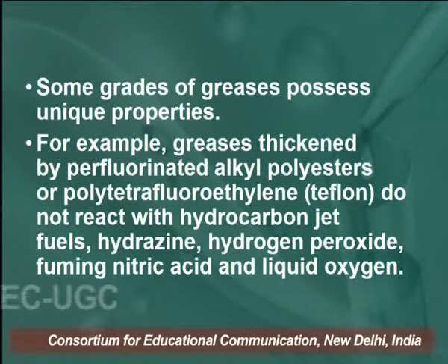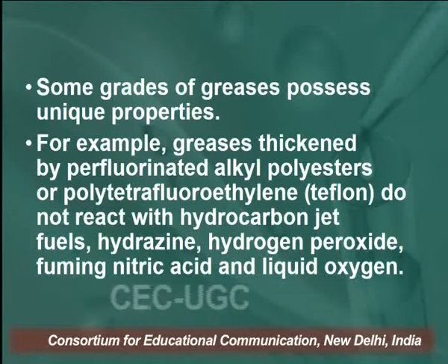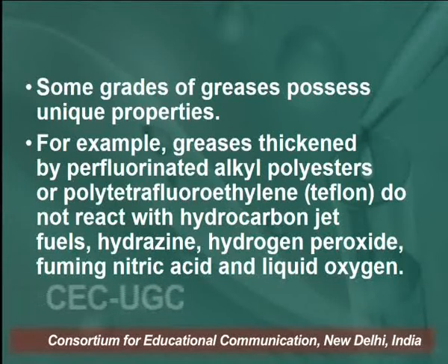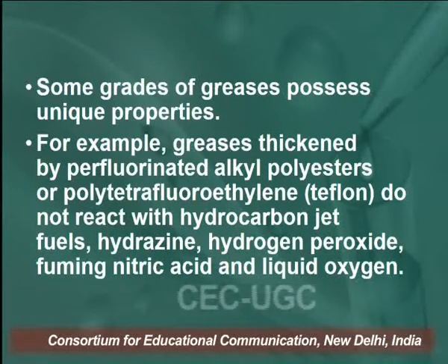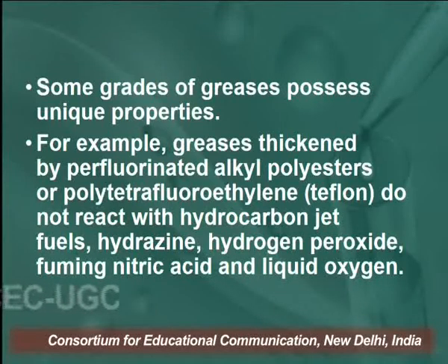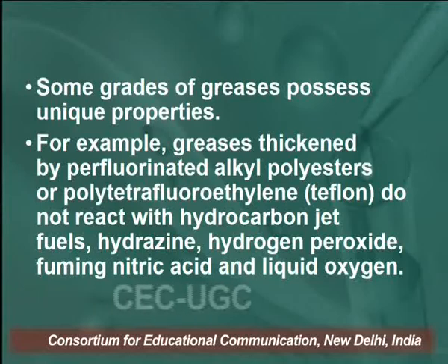For example, greases thickened by perfluorinated alkyl polyesters or polytetrafluoroethylene, that is Teflon, do not react with hydrocarbon jet fuels, hydrazine, hydrogen peroxide, fuming nitric acid, and liquid oxygen.